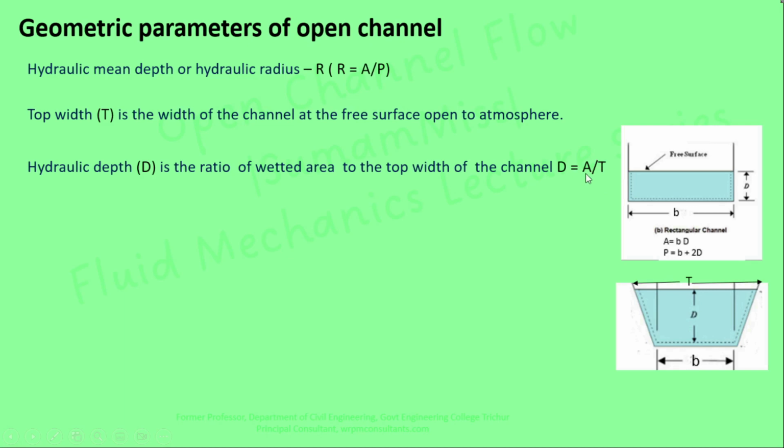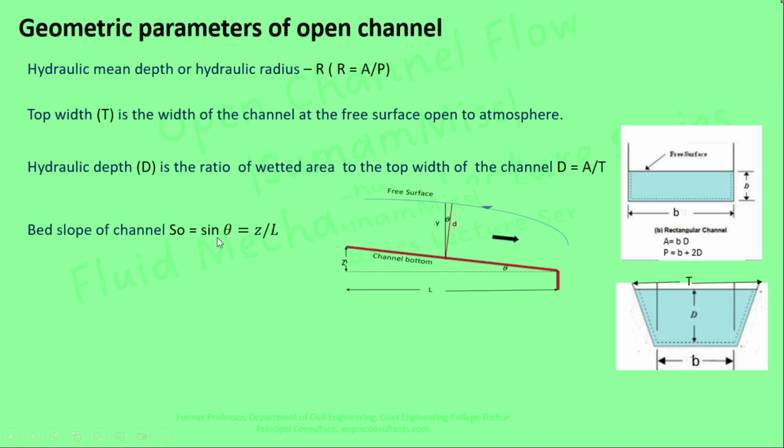A is the cross-section area and T is the top width of the channel. Another geometric parameter is the bed slope. So this is the longitudinal section of the channel. The elevation difference between these two sections is equal to Z, and the length of the channel is equal to L. So bed slope S0 is equal to Z by L. If theta is very small, instead of tan theta, we are representing that as sin theta.